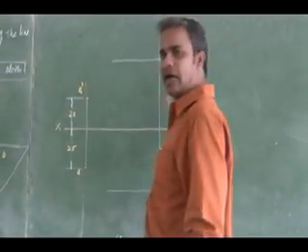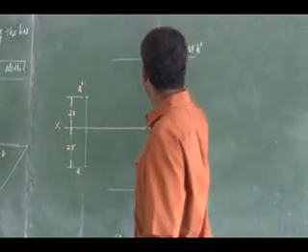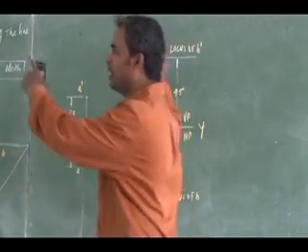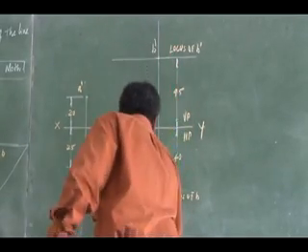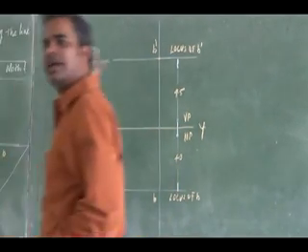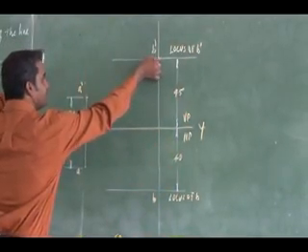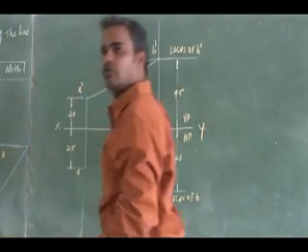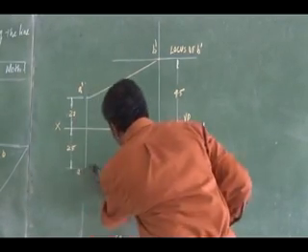The locus of B dash, we got the intersection with the another end projector, right? Intersection with the other end projector is here. Okay, with the locus, that is nothing but my B dash. Okay, that is my B dash. This will be my B. Can you draw the final projection? So A dash I have, B dash I have, A I have, B I have. I can just connect A dash, B dash. So this is my final front view. Okay, this is going to be my final top view.